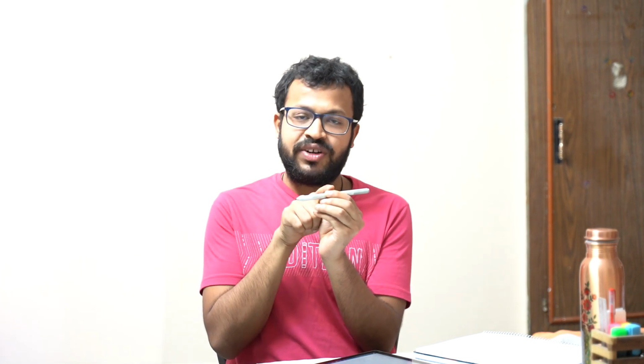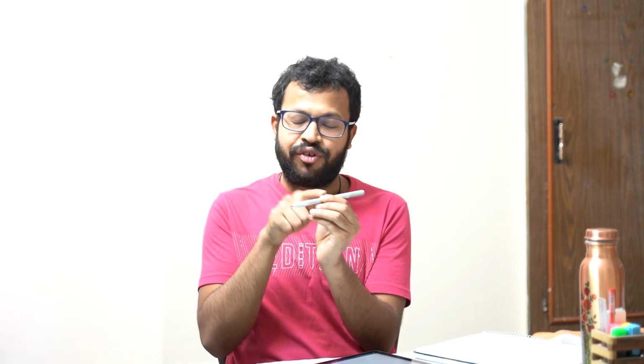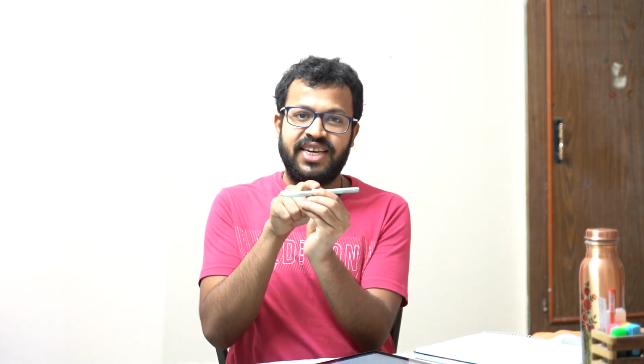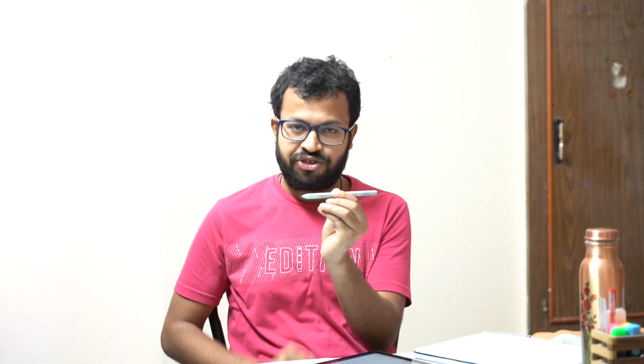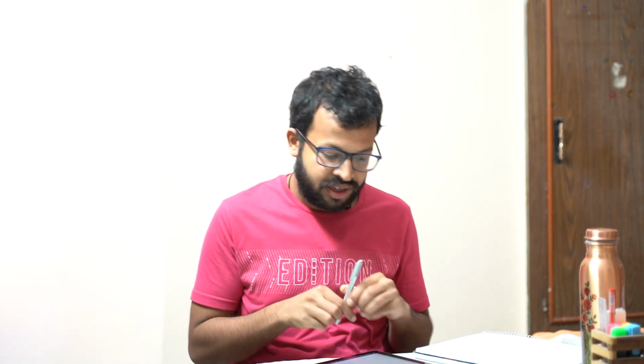So coming to the conclusion here, for the central difference or piecewise polynomial scheme, phi small e was given as the average of the surrounding points. In the upwind scheme, we considered the upwind direction, and we said that phi small e is the same as phi at the upstream point. In the QUICK scheme, we took 2 points on the upstream side and 1 point on the downstream side. We fitted this quadratic polynomial and interpolated for phi small e.